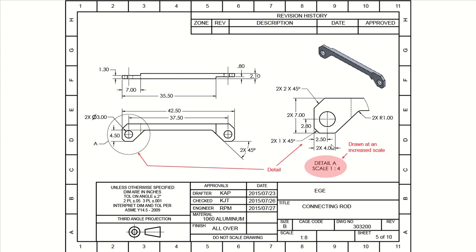And of course we are scaling it up. We're drawing it like 1:4, original 1, and you make it bigger 4. So that's what the scale is about. So you show, this is my detailed view of A, and don't forget this: when you say the detail view of B, then it's got to be B here. So make sure your label has to match where you're pointing it out.